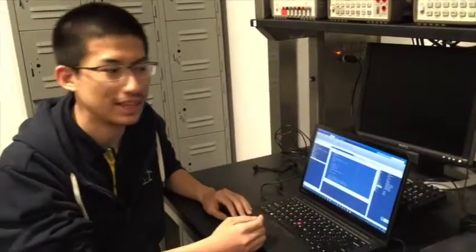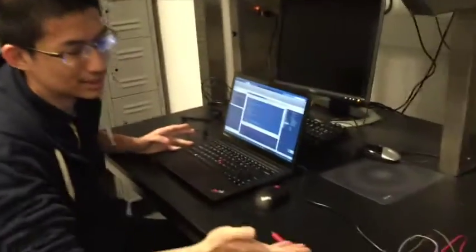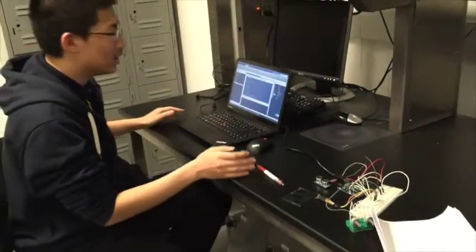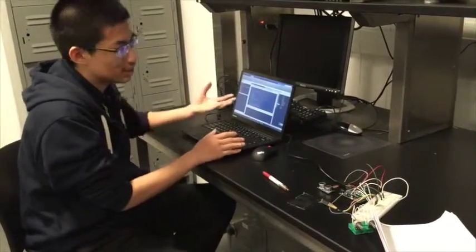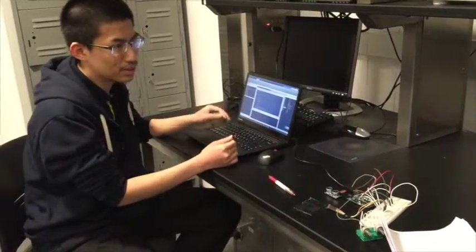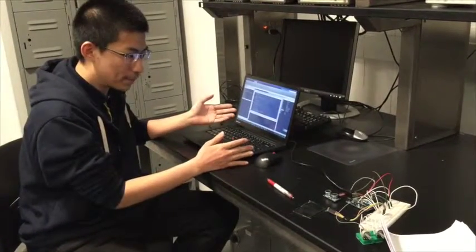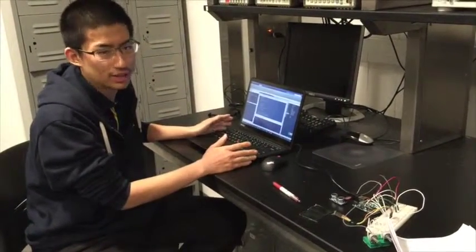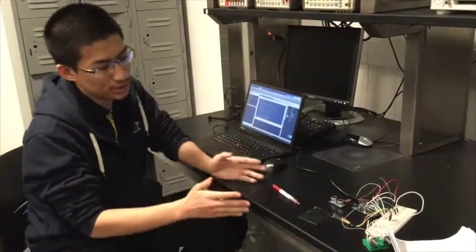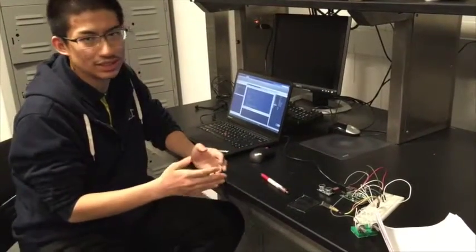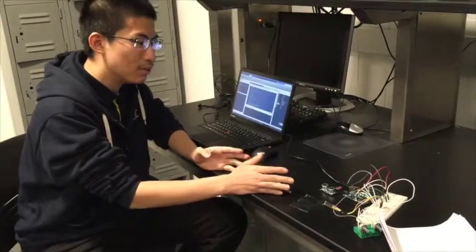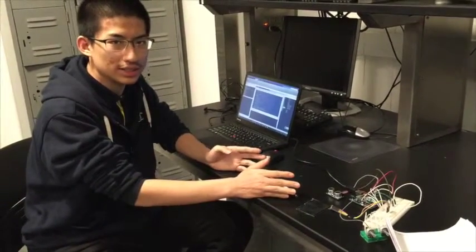Another difficult point is that these two systems work at entirely different frequencies. MATLAB, because it's reading the audio file and processing it, is very slow, about 5 Hz. But the Arduino only deals with the sensors, so it's quite fast, working at about 100 Hz.